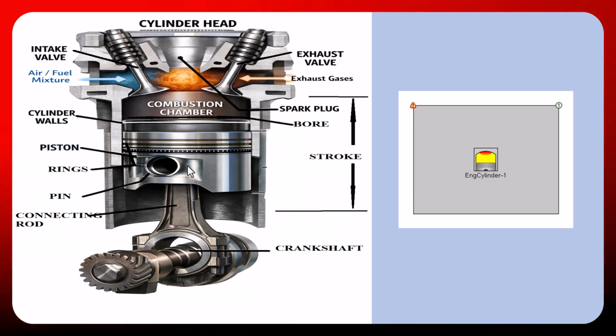Okay. In this picture we have the combustion chamber. It is the volume above the piston when it is near TDC, where fuel combustion occurs. Its shape affects turbulence and flame propagation, and is directly linked to compression ratio.